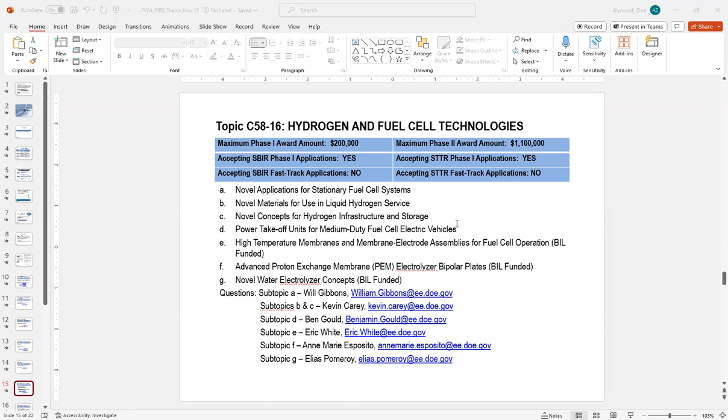Another area that's of interest is composite materials that could be used for components of a vessel for liquid hydrogen storage. One of the key advantages of liquid hydrogen storage is its higher density and also the ability to work at lower pressure. So we could have something that's lightweight and has the ability to hold more hydrogen by gravimetric capacity or volumetric capacity too. Again, like looking at seals, the key parameter would be the ability to handle temperatures from 20 Kelvin to ambient.